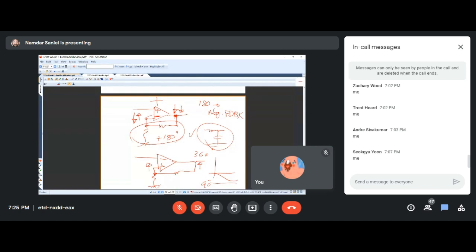I think your question was, how would we get 360 degrees back? In this case, where we have resistances, never. If we are careful and we use the negative input terminal in the feedback, never. But if these were not purely resistive, then we could get some phase change. And if that phase change adds up to 180 degrees, we have an additional 180 degrees to the original 180 degrees.